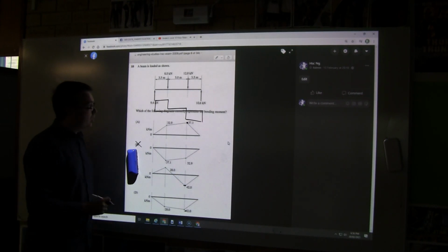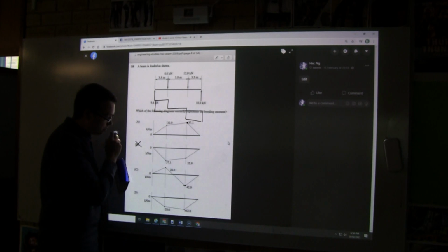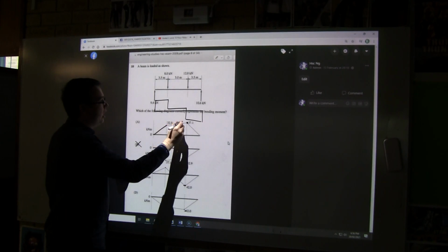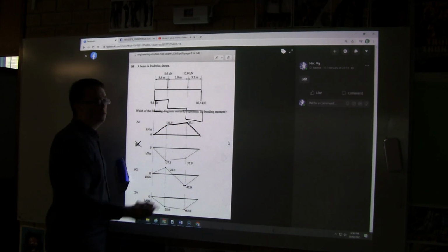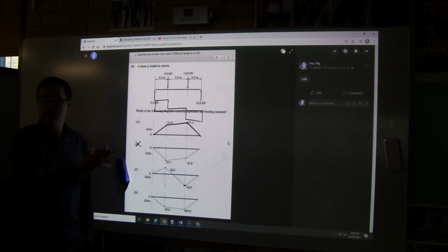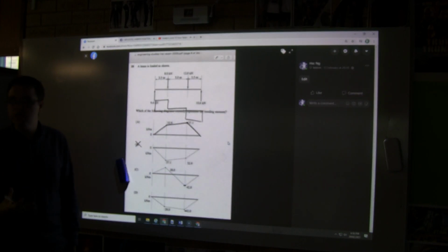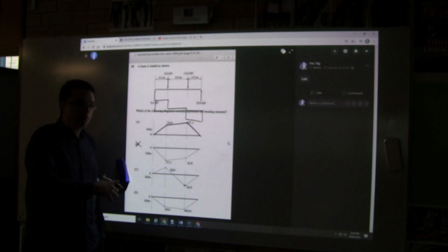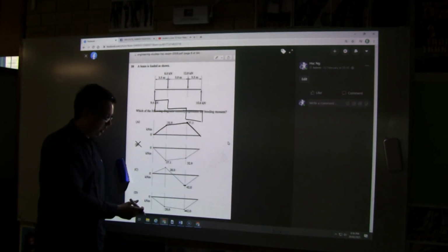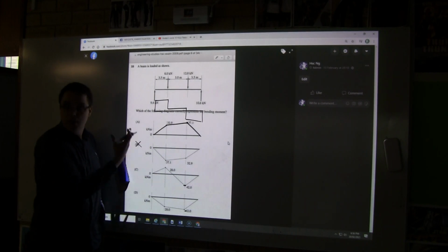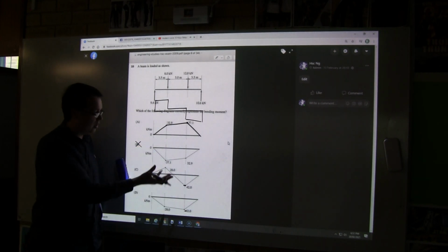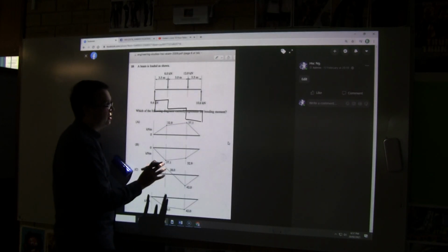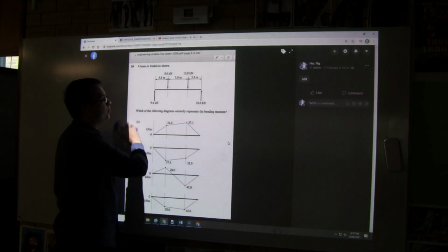The next thing we can see is, what we've got in here is a number that's positive, and then a little bit more positive, and then a big negative. We've already said that it's A, but we're really honing in on that it has to be A, given this particular load condition. This really needs to be a cantilever to explain how we could get this load condition here, and here we have just the wrong values. When we actually do a calculation, we see that we get the wrong values, aside from the fact that the diagram is inverted. The diagram being inverted shouldn't be enough to rule it out, but the answer is A. Okay, click on the next one.